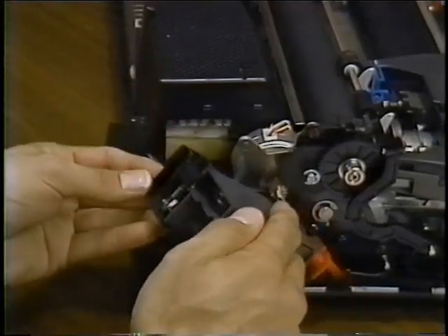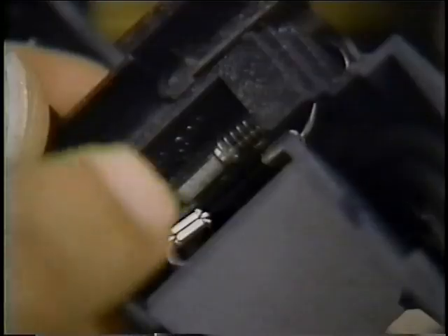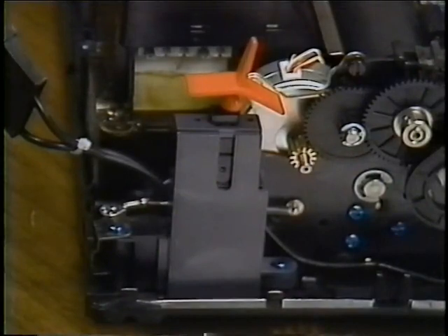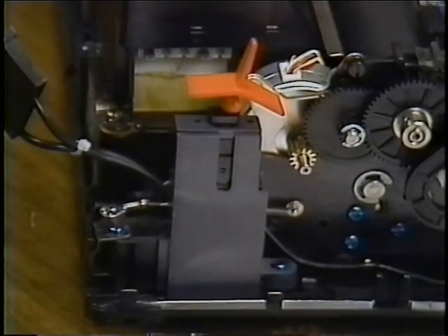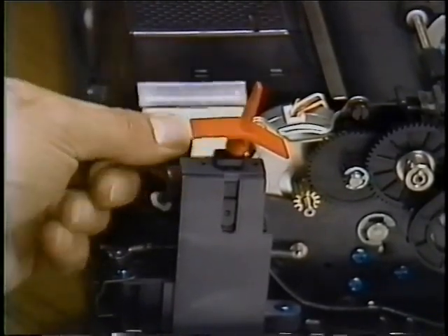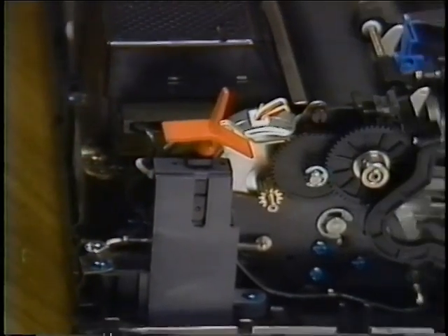This is the inline fuse. You test this fuse by performing a continuity check. After checking the fuses and before turning the machine on, be sure all of the connectors are on tight and the power supply cover is in place. This concludes the power supply checks.